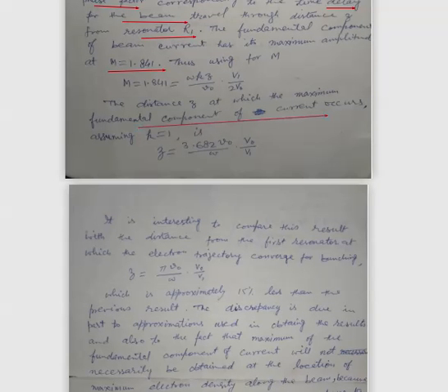So if we now compare this result of z with the value obtained in our previous lecture for the distance at which the bunching will take place, that is when the electron trajectory converges to bunching, this equation for z has its value z equal to pi small v0 upon omega into V0 upon V1.